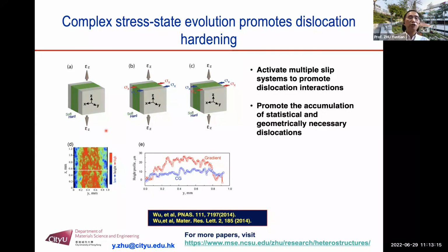However, when the stress increases to a certain level, the softer core will start to deform plastically. When it deforms plastically, to maintain the same constant volume, the softer core will shrink faster sideways, because we know in a tensile test in the elastic state, when you make this elongation, the sample will shrink sideways because of the Poisson's effect.